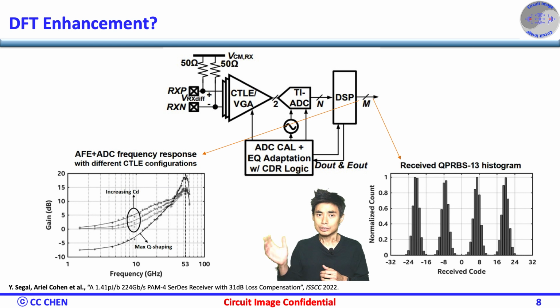Even though the equalization is perfect, we must observe the AFE linearity and even optimize its linearity during the link training or background calibration if needed. Lastly, to achieve a lower bit error rate, we need to monitor the thermal noise or the voltage distribution such that we could even optimize the biasing over PVT to reduce the noise besides just reporting the noise contribution during